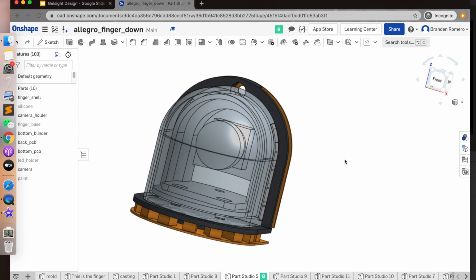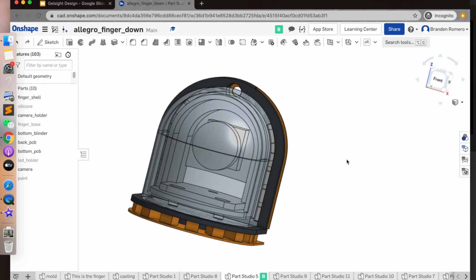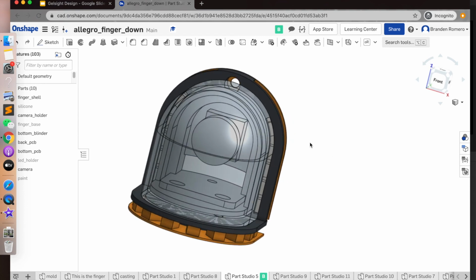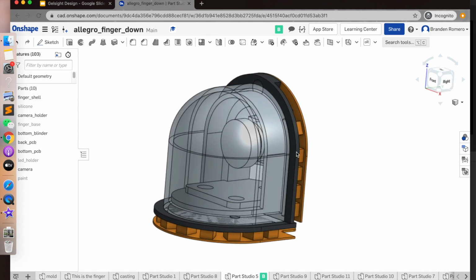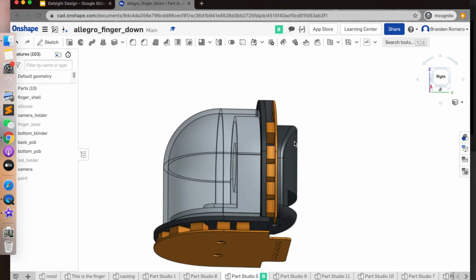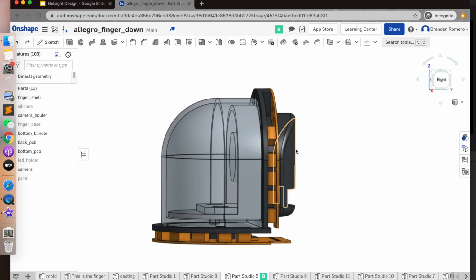It has, I think, an M8 lens adapter, so we can mount lenses with a 140-degree field of view onto that sensor, which is nice because we can make this sensor a lot more compact with a larger field of view. But it does cause some distortion as you have a larger field of view with the camera.